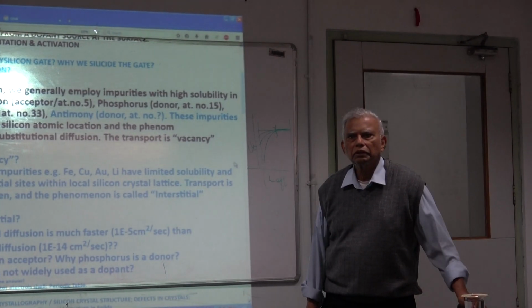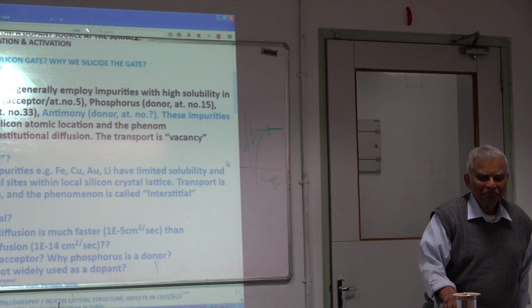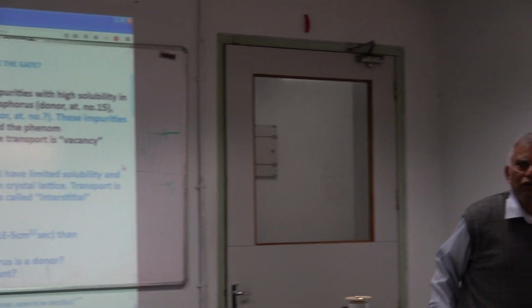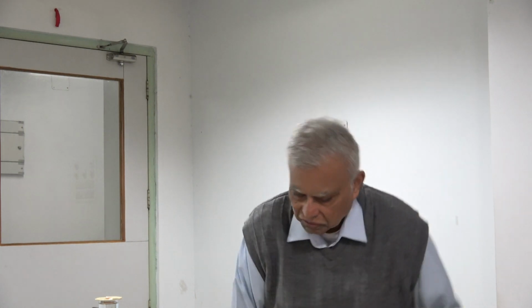In substitutional, we have to throw out one atom and then introduce another one. You have to break some very strong bonds to displace that particular atom in the lattice, right? Well, the interstitial just looks for some space, and once it moves in, it squeezes in pretty quickly. Okay?